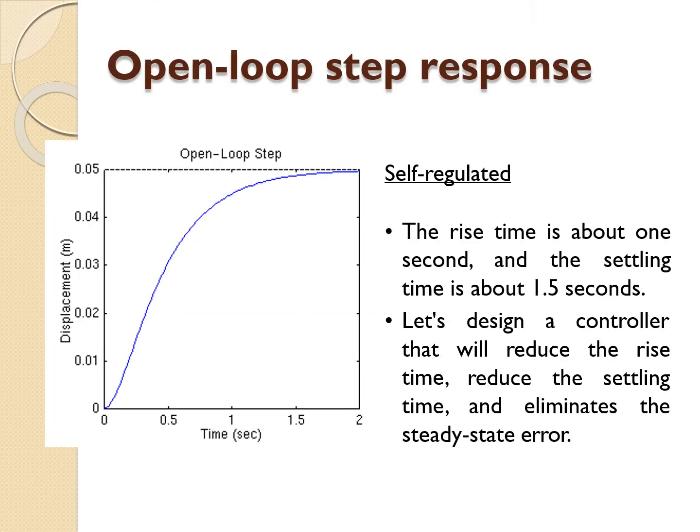Open loop step response is the testing that we do by manipulating the opening of the final element for the manipulated variable. In other words, we regulate the manipulated variable to see the effect on the process variable.